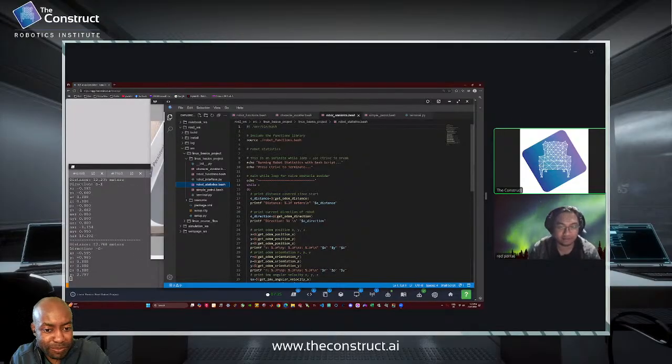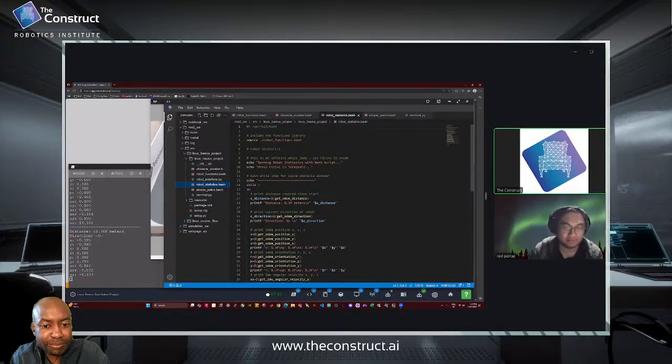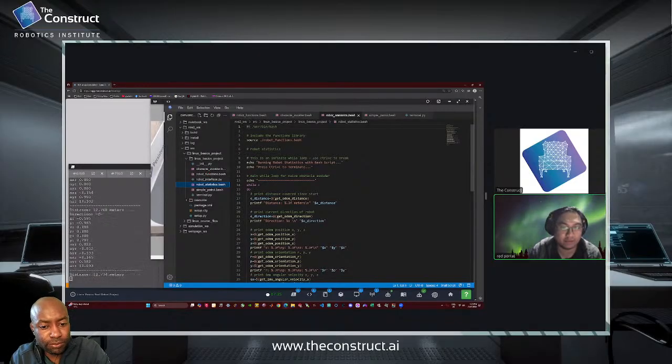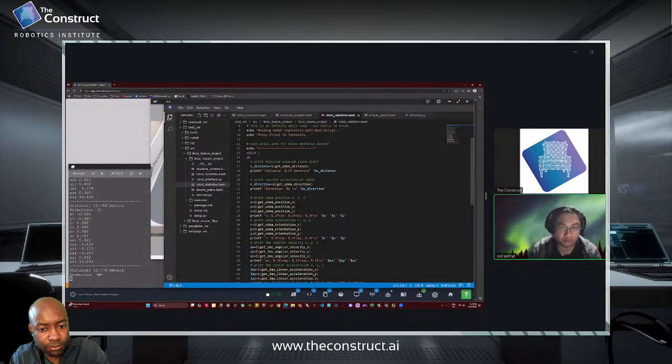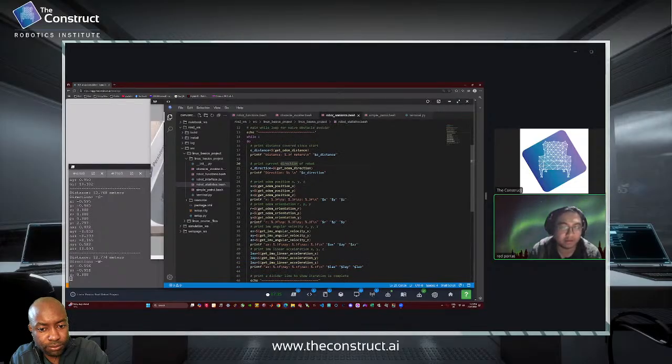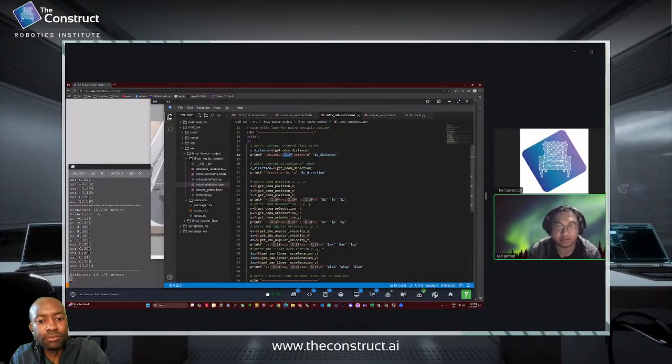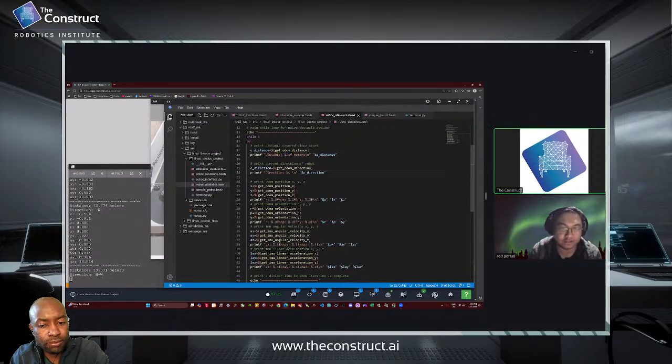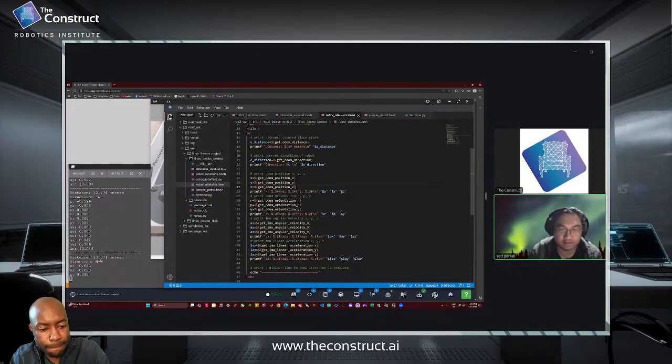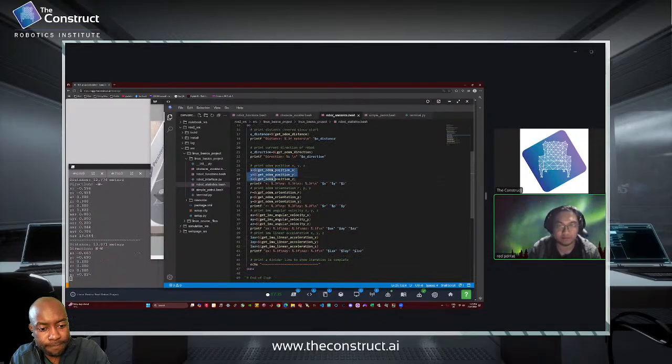Oh yeah, this one, the robot statistic. For robot statistics, same thing as for obstacle avoider. I put the source that robot function and the shebang as well, and print it. And inside my while loop, same thing, saving the data into the variable of distance, and because it's a float, I put this line to make it three decimals, and for the O direction, I put S because it's a string. So basically everything is the same. It's just the printing convention that is different.